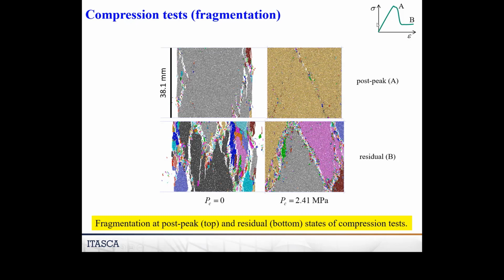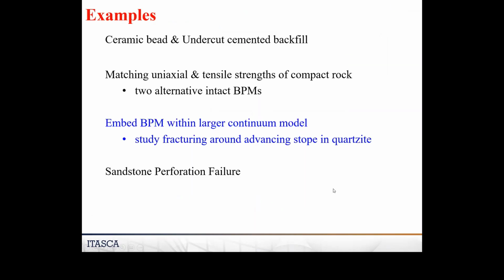Here you see the beginnings in the post peak of what looks like maybe a shear fracture. If you keep loading it, sure enough, it forms these shear fractures. This is now a new mechanism that kinematically can sustain deformation. That's why you reach a residual now, and it's not changing anymore. So this is very much like what we see in rock. We see axial splitting unconfined. We see shear fractures forming, excuse me, when you're confined.